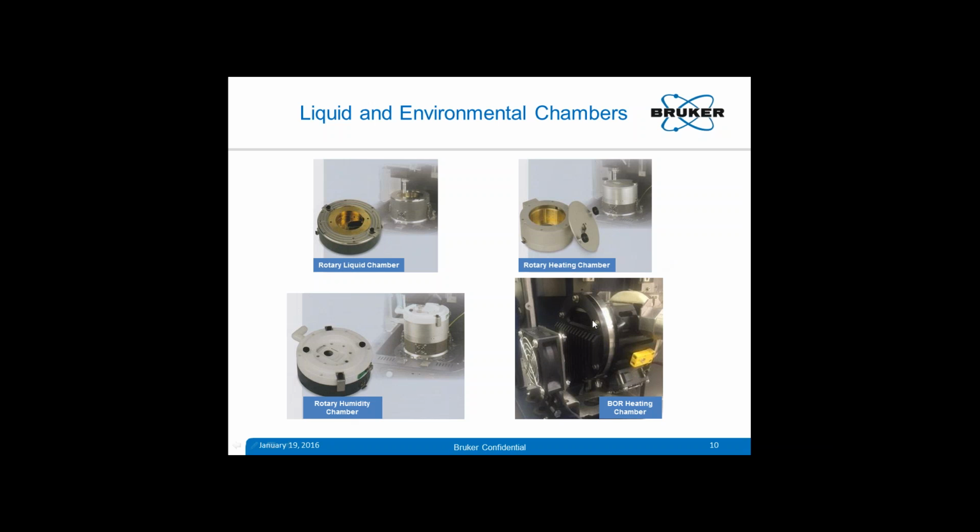And we have an environmental chamber for the block-on-ring drive, recently designed, which takes into account the heat produced due to friction. So it has a cooling facility so that you can control the temperature of the loop used in this particular test to a desired level.